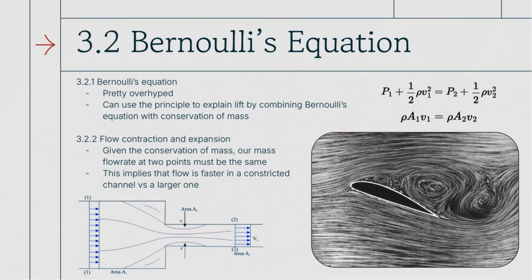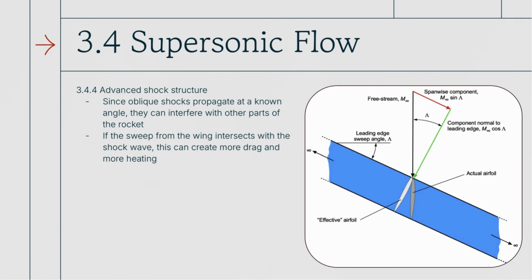NACA airfoils are a convention used a lot that defines the shape of the airfoil. It can be stretched, squashed, expanded, and it can have humps on the bottom and other odd features. The airfoil shape can change throughout a wing, and it will often be optimized depending on how far out on the wing you are. So essentially the shape of your airfoil now changes because you're taking a diagonal slice of the wing instead of a perpendicular slice of the wing. Make sense?